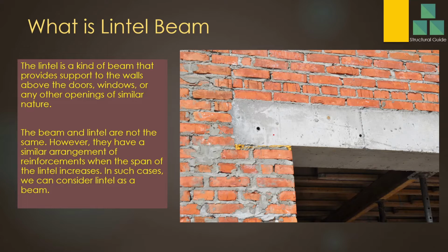In a normal reinforced concrete structure, a beam is supported mostly on concrete columns. There will be two columns on either side of the beam. One more difference is the size. Lintel beams normally have a shallower depth due to the smaller load that they carry. But a reinforced concrete beam may have a higher depth due to the higher load. Brick wall loads and slab loads will be carried by those beams.